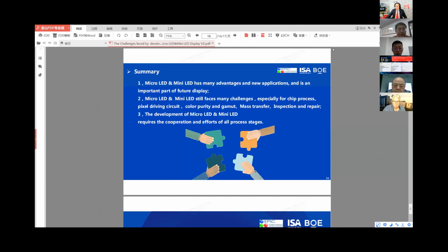In terms of the black direction, there are a lot of challenges, of course. If we don't do the black, the contrast will be compromised. If we do make the black silicon, it is going to impact the overall brightness. So how to make the black layer, how thick it should be, and how we have an overall design, and also the process design. I think there will be a lot of improvement to the display quality if we do them well, and also the price and cost. We have to consider the overall cost if we want to promote the product. So in terms of the direction of low cost, the black gel or black picture as the major solution, I think they can help us drive down the cost even further.